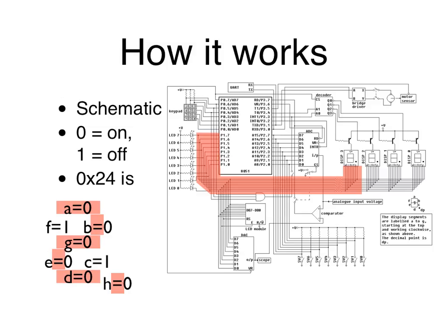And so if you check the 7-segment LED, there's what they call A, B, C, D, E, F, G. So A is the top segment, B is the right top, C is the one below it, D is the bottom, E going up. So it's a clockwise order, and then G is the middle one, H is that little dot.